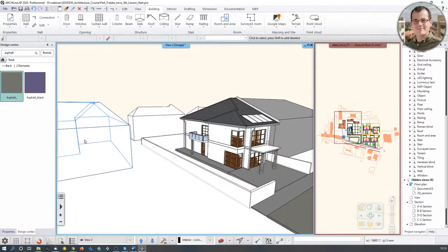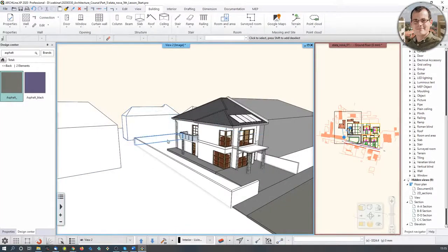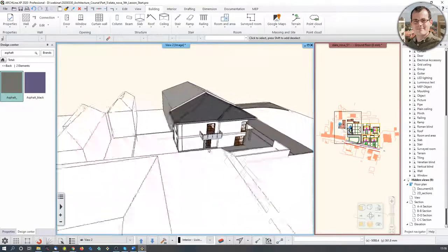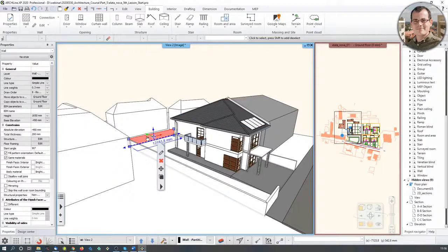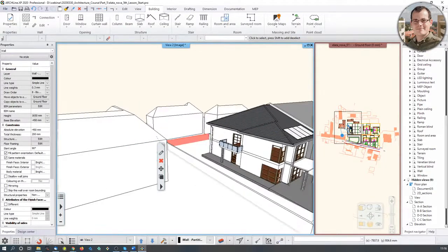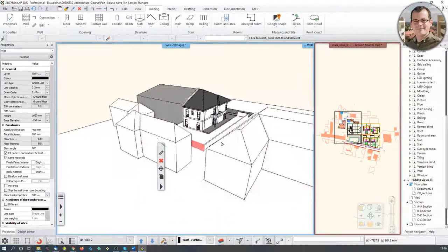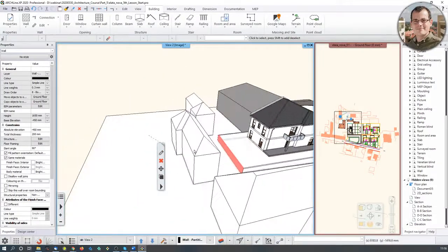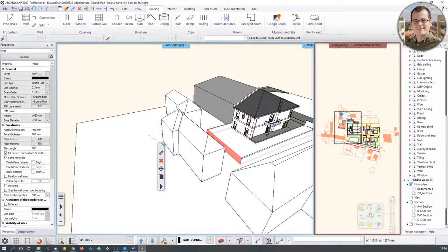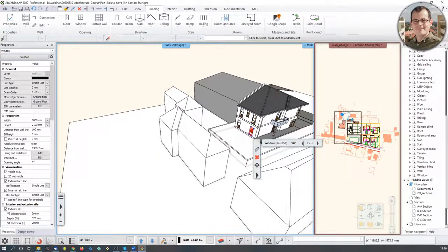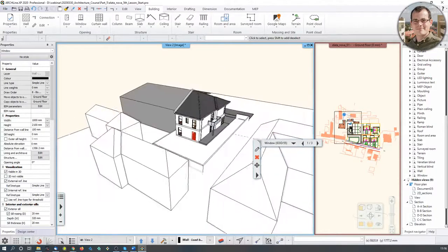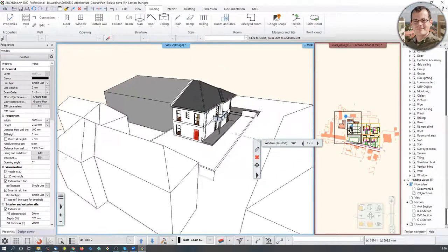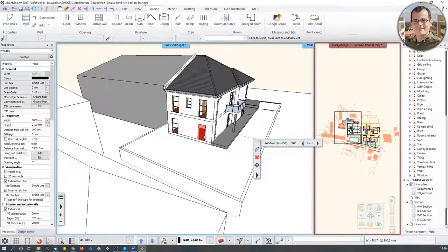If you want to orbit around something, if you just hover your mouse over it and hit the shift key, then it's going to orbit there. Or alternatively, you can just manually pick an element around which you want to orbit, hit the scroll and shift key and move your mouse, and you see how the orbit center just jumps to another place. Let me show you with this window. So up until this point, this was the rotation center, but now we are changing to something else, and here we go. So that's easily how you can navigate between things.